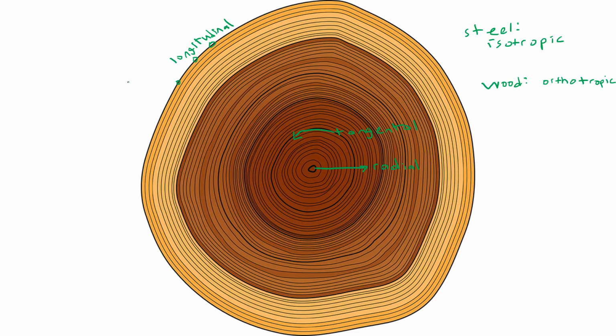It should not surprise us that wood is a material that is much stronger in the longitudinal direction than in the radial direction or in the tangential direction. Structural strength in living organisms costs energy. And since trees require more longitudinal strength than tangential or radial strength, that carries forward into the wood as an actual final product.